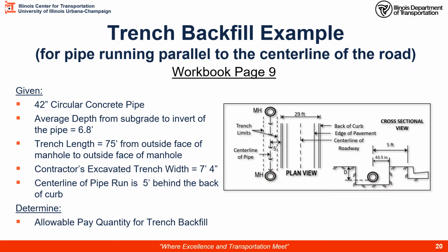The next thing we need to check is what will be the length of our pay. We know it's 75 feet from face to face of the manhole, but if you remember correctly, we need to subtract off 3 inches from each manhole to account for the trench backfill material that is included in that manhole pay item. So that's going to be 75 feet minus 6 inches, or 74.5 feet, will be the pay length.